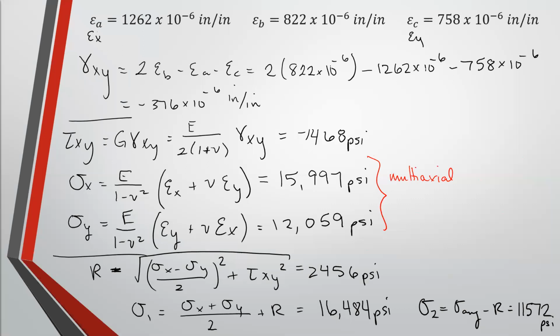Okay, so now we want to line those up with sigma A, which is bigger than sigma B, which is bigger than sigma C. So our third principal stress is 0, right? Now we're assuming that because if we actually calculated it, maybe there'd be some small value, but we're assuming this fuselage to be plane stress.